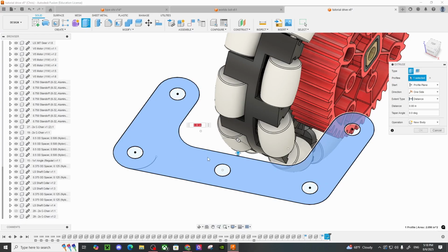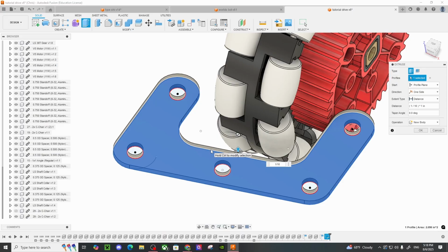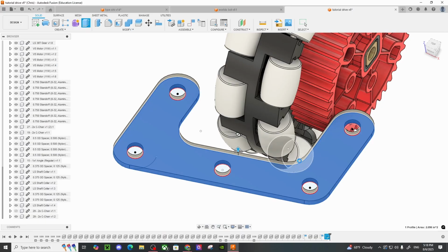Once you click on it, pull this arrow up a little bit to get this box, and then type your plastic thickness in there. You can do the fraction if you want. 1/16 should be what most people are using for plastic. You could use 1/32, but most plastics people are using are 1/16. So type that into this box and then hit enter.